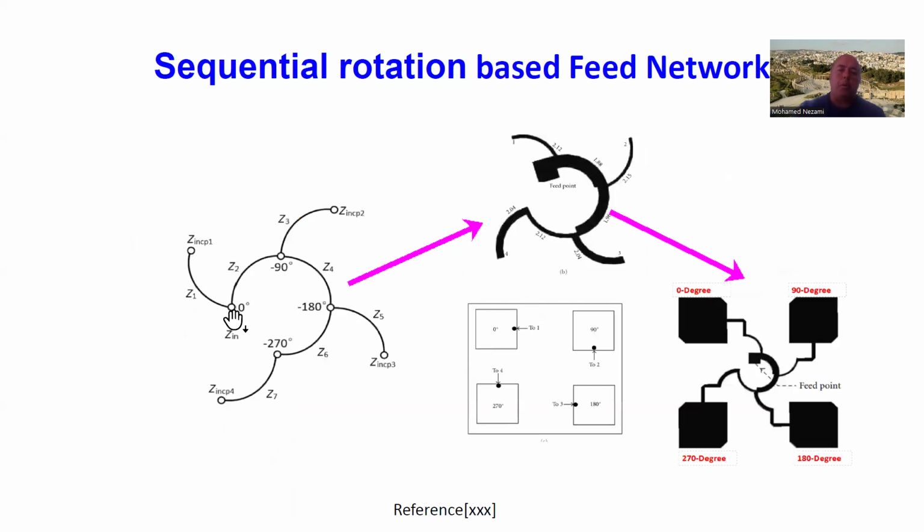So again, now we go from, you can see the diagram in here. We have a network that has basically 4 discrete phase shift levels, and at those points we diverge into an antenna element. In this case, we are feeding here and going this way clockwise, and that's called the designation because you're doing the right hand, so it's the right hand side circular polarization. And that's the microstrip. Of course, the impedances vary, and you can see that in here. And we'll show you how we come up with these dimensions in a minute.